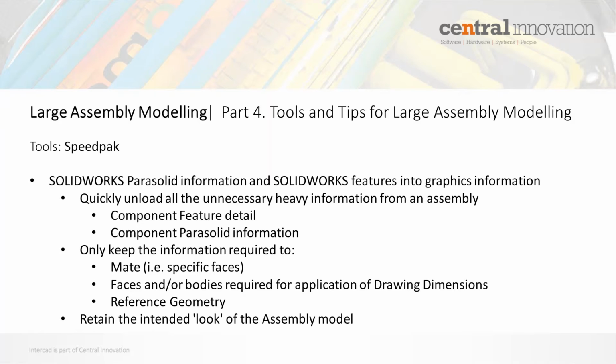And the concept is that you can still see what the assembly looks like in your graphics area on the screen, but you only need to retain the model information that's critical to mating and keeping the assembly together. So in the sense of using SpeedPAK, you're really speeding up what you're seeing on the screen. It increases your performance, but you still get to see effectively the whole model.